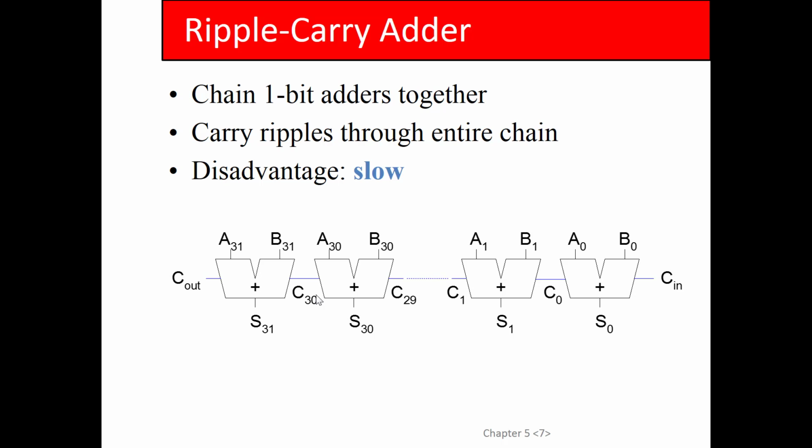And every sort of arithmetic operation imaginable is also based on an adder, even floating point. Even when you do a floating point operation, it's doing comparisons in the exponent field, it's doing adding in the exponent field if you're doing a multiply, it's doing adding in the significand field if you're doing an add or a subtract. Everything uses an add. Literally everything you do with a computer does an add at some point.